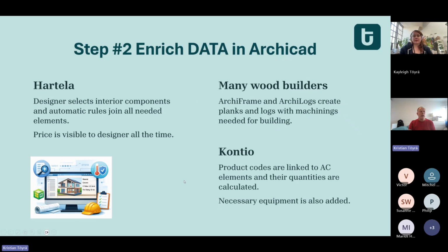In the Contio case, product codes are linked to Archicad elements and their quantities are calculated. Necessary equipment is also added. Let's say screws, because there's hardly ever screws in an Archicad model, but you still need screws to build a house. So all these components will be added behind the model inside Archicad still.